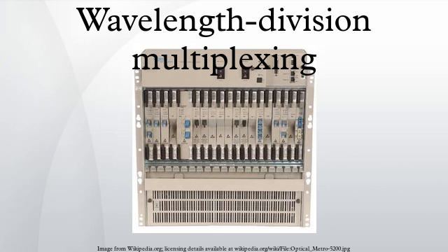Recent innovations in DWDM transport systems include pluggable and software-tunable transceiver modules capable of operating on 40 or 80 channels. This dramatically reduces the need for discrete spare pluggable modules, when a handful of pluggable devices can handle the full range of wavelengths. Wavelength-converting transponders.